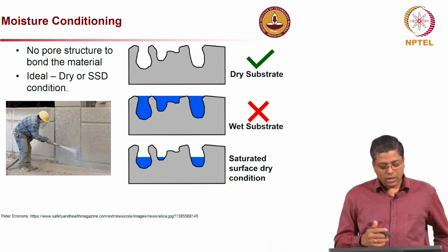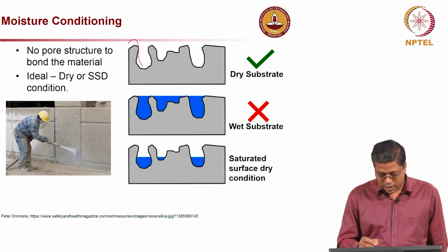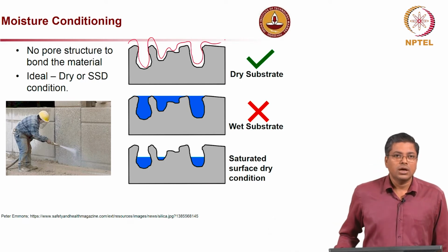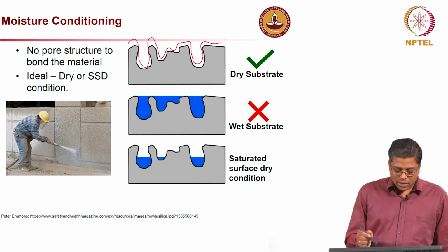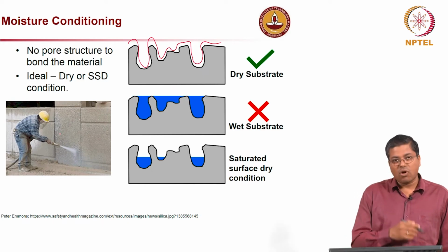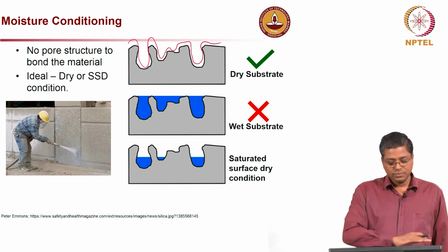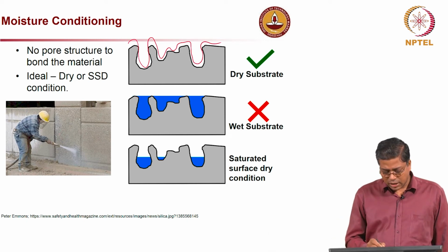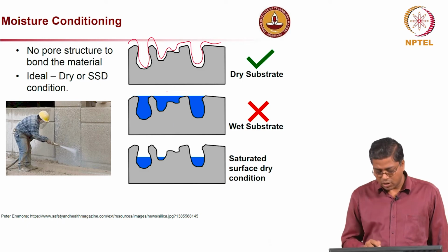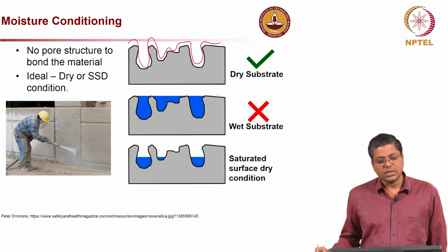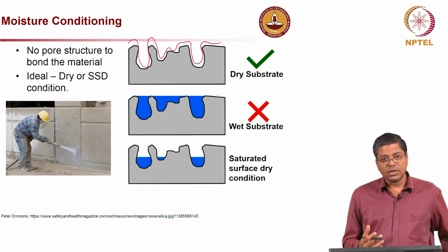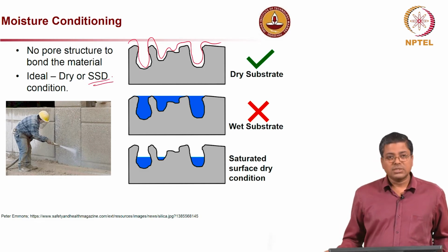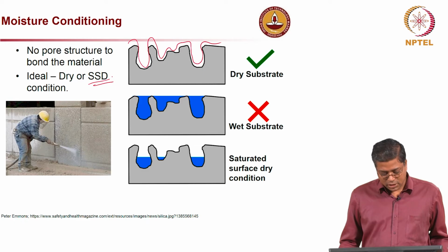Now, after removal of concrete, you might expect that there will be uneven surfaces, micro level uneven surfaces on the concrete surface. Imagine in the case of a floor, this may not always be the case, but water can get filled in these fine pores. So it is very important that the water from the fine pores must be removed, or mainly you must ensure it is at least in a saturated surface dry condition.